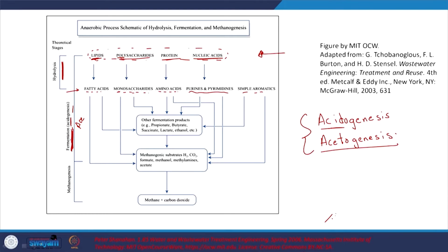And typically we are looking at fermentation, let us see. Note that here there is no oxygen involved. In a redox process you are going to have transfer of electrons. In the aerobic activated sludge process, oxygen was the electron acceptor. Here, if it is fermentation, the same compound will lead to a relatively more oxidized and a relatively more reduced compound. Or in the case of methanogenesis, you can have hydrogen as the electron donor, carbon dioxide as the electron acceptor and such, let us see. So, that is something to note, we will come back to that later.